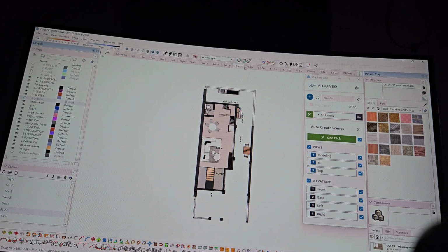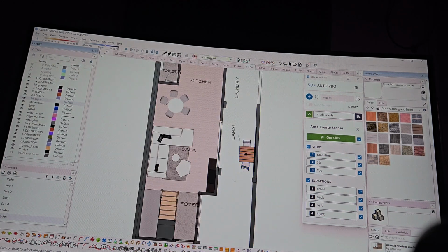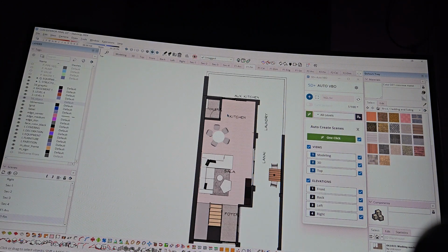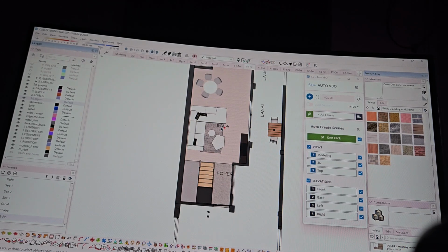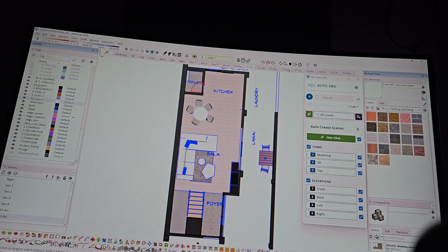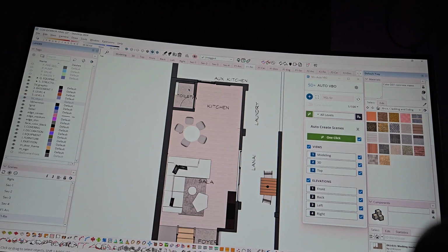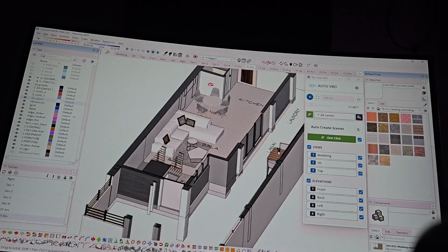So this is architectural. What finishing does is it turns off the tags of the interior furniture. Okay, so I'm wondering, where did this fall under? This fell under interior furniture. Okay, finishing turned off equipment, so our fixture. So that means we can only see the things that will be bought by the owner, aside from the shell. Okay, these ones. And finishing is also good to show our tile works, floor finishes, and wall finishes as well.